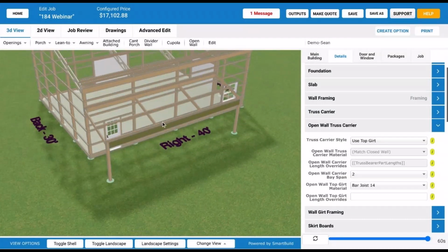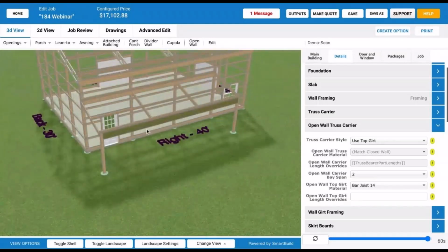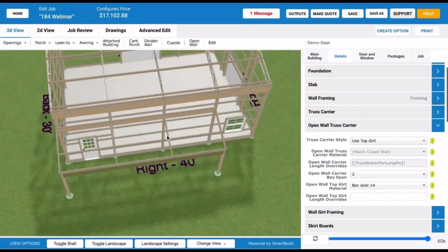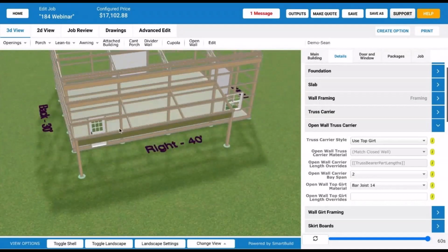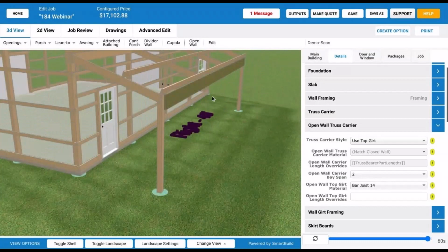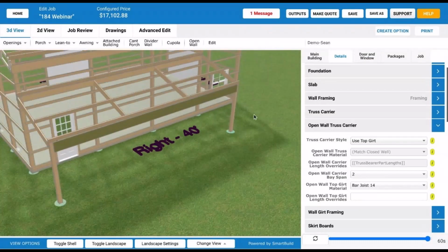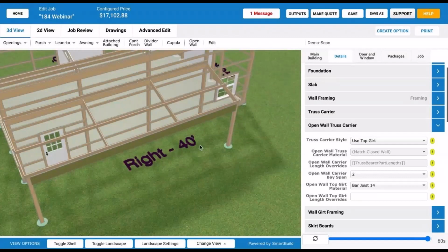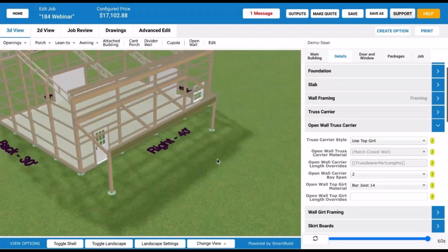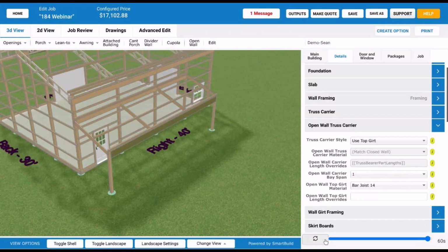So you can see that I changed the number of bays that it's made to 2. Based on just my spacing here, that just got rid of both of these bays. So now I have this spanning across this entire porch. It's completely open here. There's no post required here because I have this structural header. You'll have to talk with your engineer about what's going to work, but you can make those things happen where you can span across the bays.